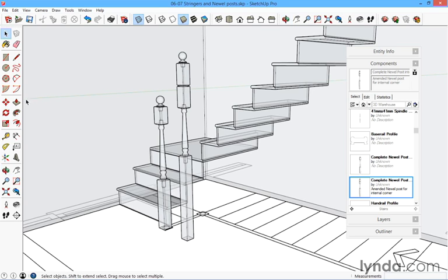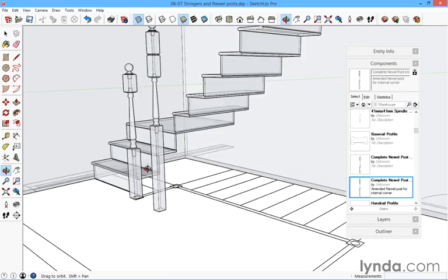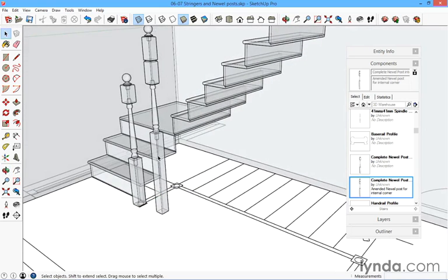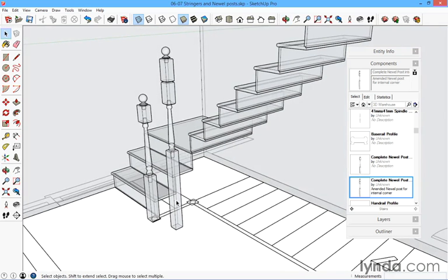Now if you haven't got these, then the heights that I've got are, for this bit you could create one that's about 1200 mil high to that point. You could go to the top, which would be about 1325, and this one you're looking at something that's about 1925 as well. So 1325 for this one, 1925 for this one. Just create a 100 by 100 square and then pull that up and turn it into a component just to make life easy for yourself, or a group. It's not really important for the purposes of this, but that's the sort of thing you would need.